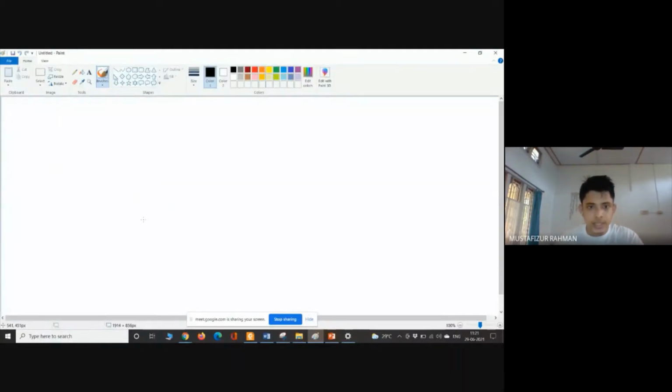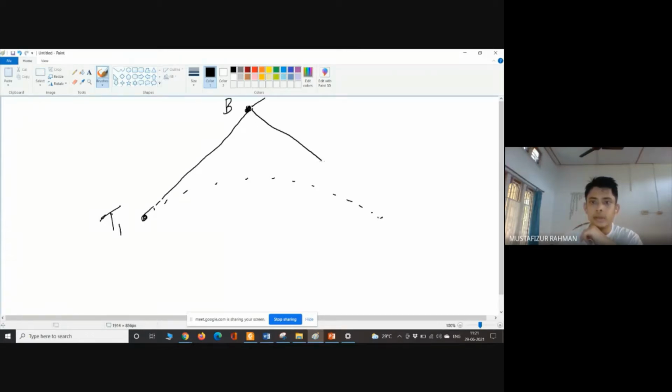Now we have established this T1 point. We know this T1 point. We know at some distance, we know this length, okay? We know this intersection point. So let's say this intersection point is B point. So we know, okay, we can join this line. It goes this way and it came this way. This angle is phi, that is the deflection angle. So this much information we have. This point is T2.